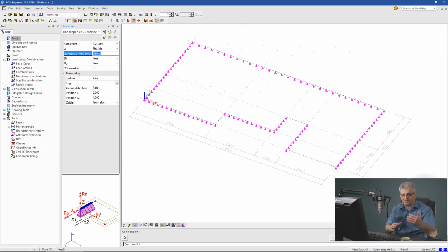What is the stiffness? The stiffness, this is the Hooke law. The stiffness is the thickness of the plate multiplied with the Young modulus of the material which is used for the wall, and divided by the height of the wall. Of course, if you have stronger material, you have stronger spring. If you have thicker plate, thicker wall, then it's also stronger. And if you have, instead of 1 meter, a 20 meter height wall, then it's weaker.